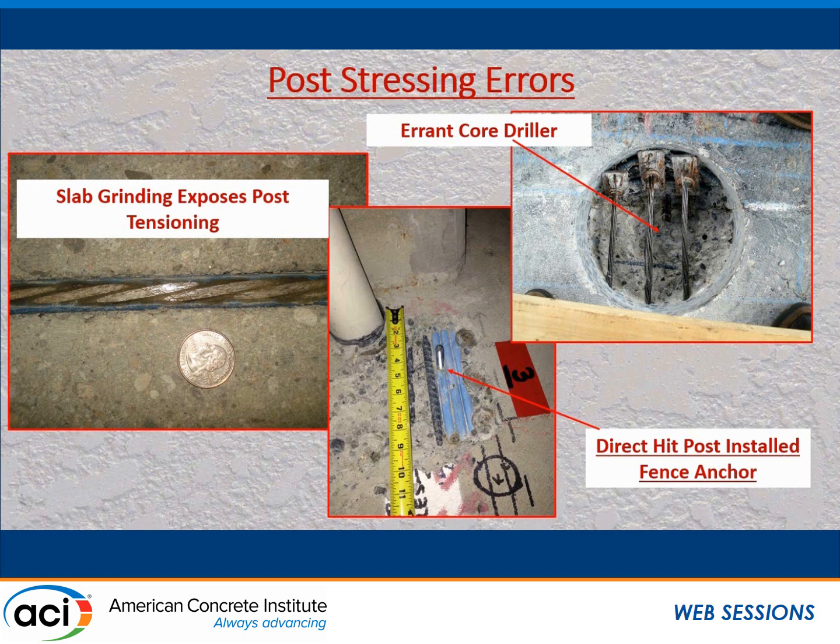So post-stressing errors, I mean, all sorts of things can happen, and you just never know quite where it's going to show up. The photo on the right, this is very common. We have existing slabs where the cables have often floated to the surface, they weren't properly supported, or maybe they got the concrete a little low, and lo and behold, the cable is right below the surface, and then you put a grinder on it, you're polishing the floor, a little change of use, and boom, there you are, and now what do you do? So we see a lot of this.